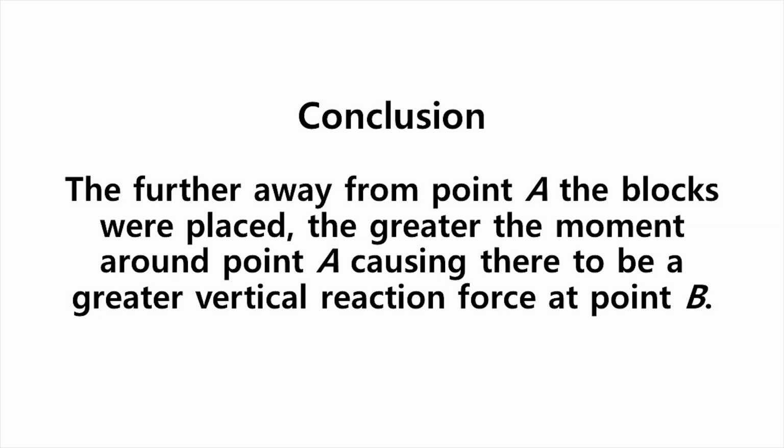Through our experiment, we came to a conclusion that the further away the blocks were placed from point A, the greater the moment around point A, causing there to be a greater vertical reaction force at point B.